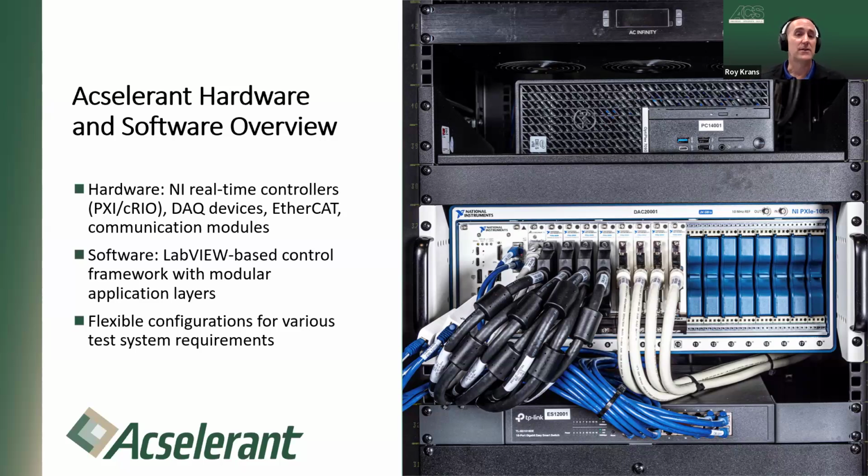It'll connect to a variety of DAQ devices, either NI-based devices or third-party-based devices. EtherCAT communication is common. We use that in a majority of our systems, again talking to NI-based EtherCAT or third-party-based EtherCAT. And then support for various communication protocols: Modbus, ARINC, Serial, CAN, that sort of thing.